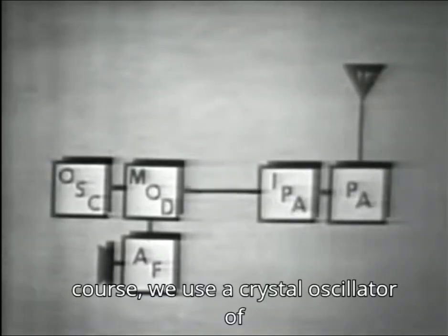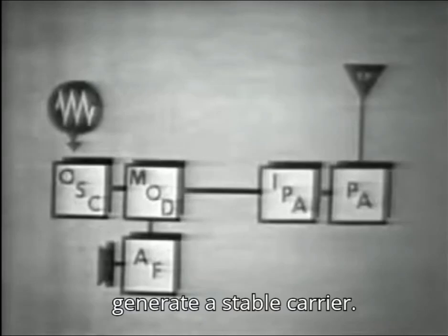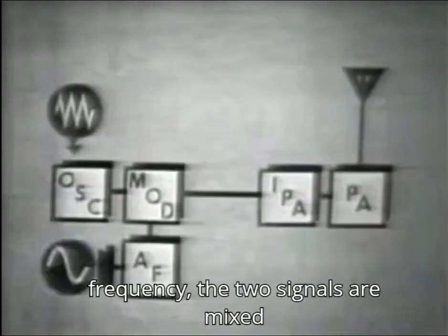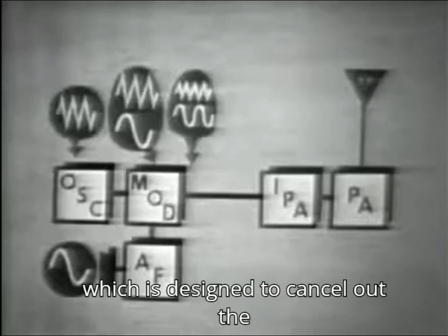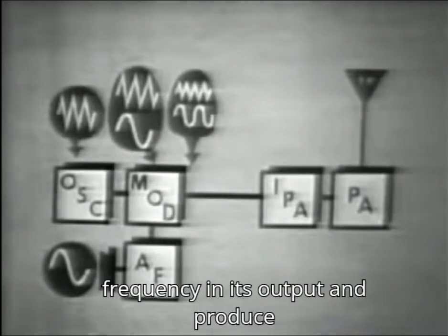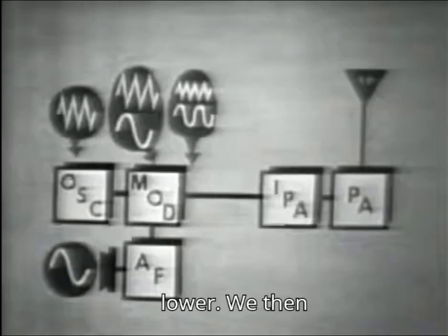Of course, we use a crystal oscillator of low frequency RF to generate a stable carrier. When we modulate it with an audio frequency, the two signals are mixed together in a balanced modulator, which is designed to cancel out the carrier and filter the modulating frequency in its output and produce only the two sidebands, the upper and the lower.